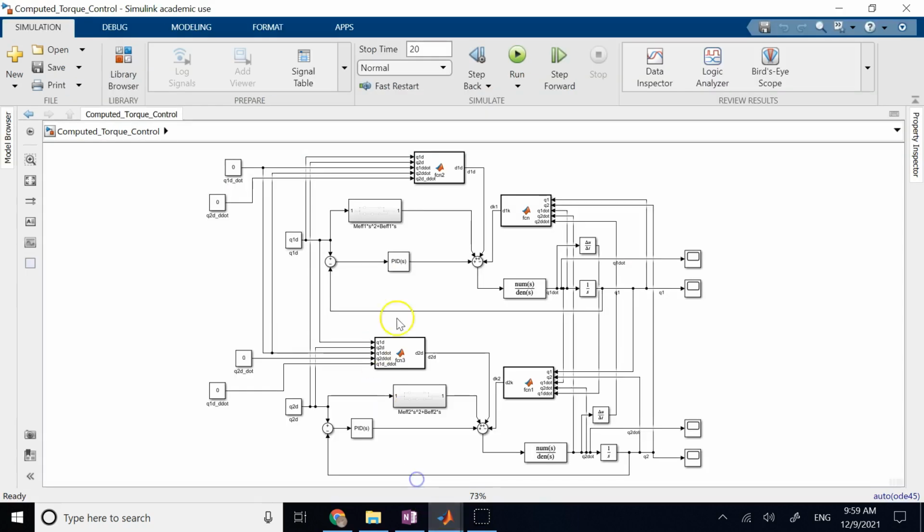Remember, in reality, there are saturations here. And if you apply saturations, the system will never behave the way it is. It is going to show you some big variations, big oscillations in the response. So in reality, the saturation is what limits the power of your control system. How many amps, how many volts you can draw out of your controller or its power sources.